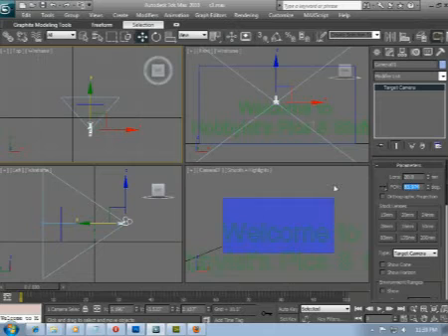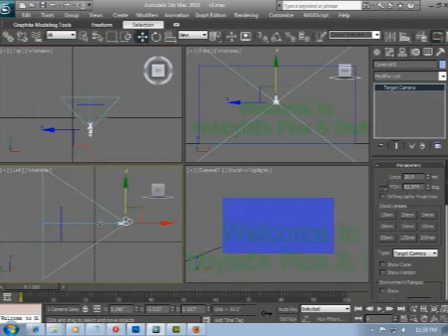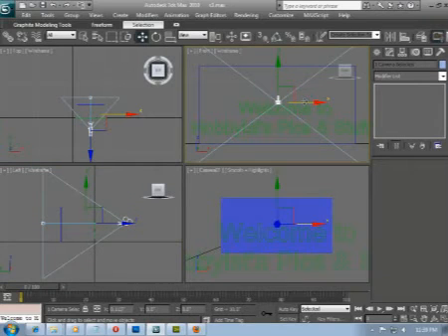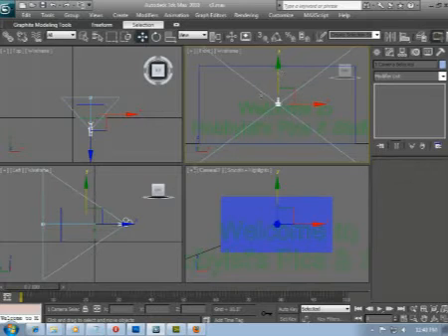Okay, there's the whole box. Now we want to use the front view to center the camera a bit better. But first we want to select the line between the camera and its target, so we move both. That's probably easier in left view. Right click there to select, then click right on the line, and right click back up in front view to use the move gizmo sticks to center the camera right in the center.